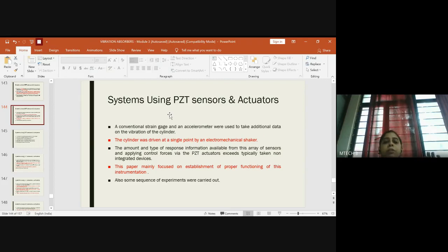Due to vibration, there will be noise as well as different modes of vibration frequency. To reduce this vibration, you should have a vibration absorber so that the vibration comes down, or else you should have a strain measuring sensor which is able to sense the strain induced due to the subjected load and the vibration.